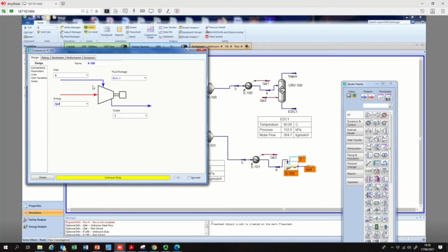So it seems like the production of vinyl chloride monomer requires a lot of energy to maintain the temperature, to pump the fluid, and so on, and also to perform the reaction at some higher temperature. Oxychlorination at 225 degrees centigrade, direct chlorination at 60 degrees centigrade. So these things should come into your mind when you're going to manufacture vinyl chloride monomer.